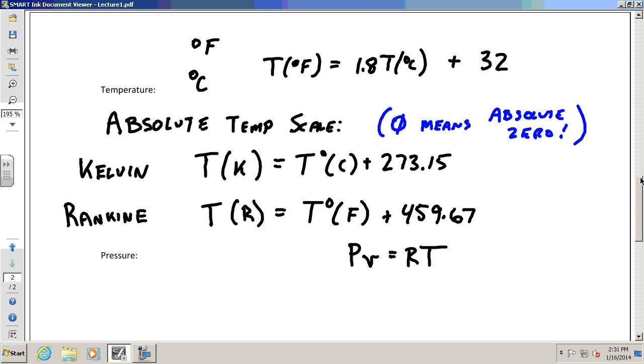Ideal gas? Now, it's a little different than what you might have seen. Maybe in your chemistry course they said PV equals nRT, or maybe they said P equals MRT or nRT. There's different ways of doing it. In thermodynamics, we usually write it like that. You might be like, well, why would we write any different? Well, usually because that V there is a little different. That V is specific volume, which I'll talk about in a moment. But regardless of this, focus in on this equation with me just for a moment. This is a very important equation.